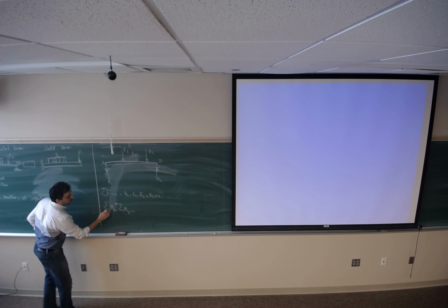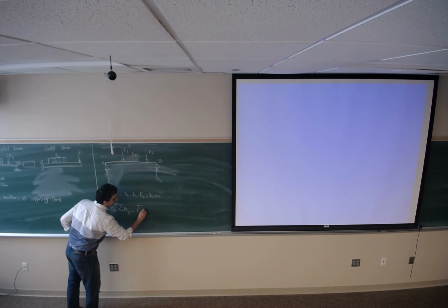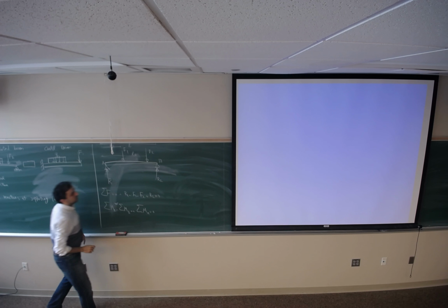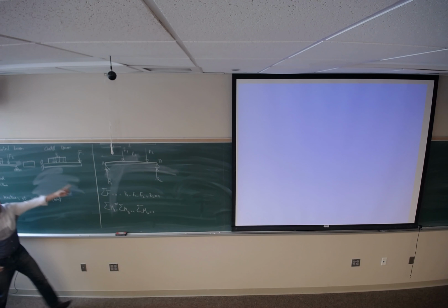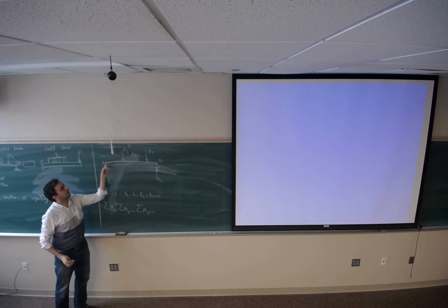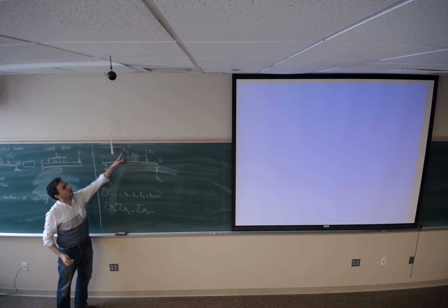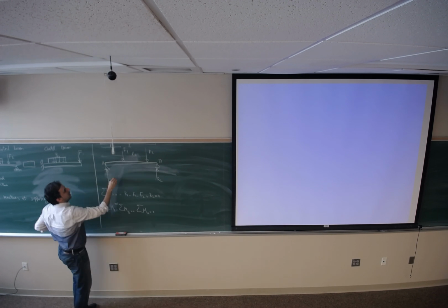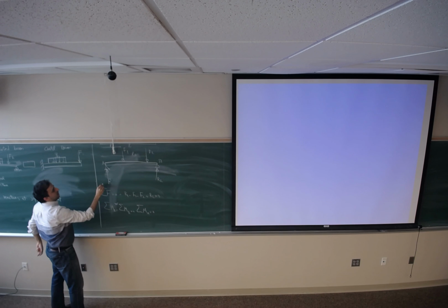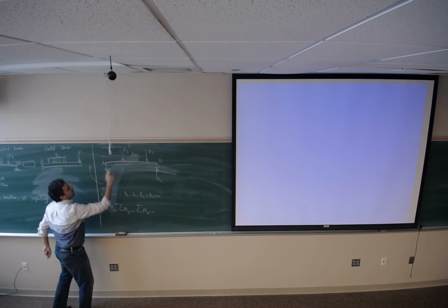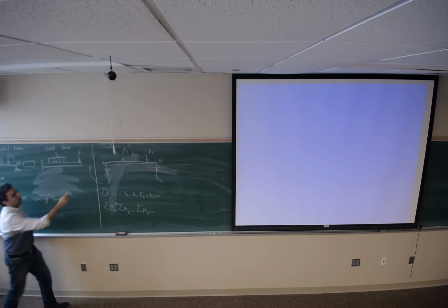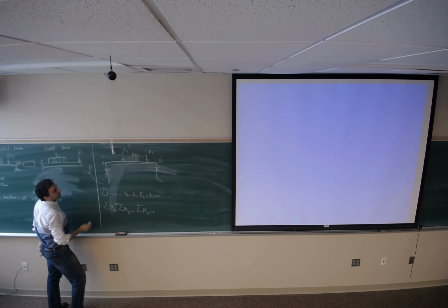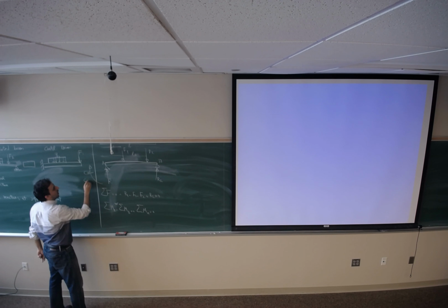I'm using sigma M with respect to point A equals to 0. So what would be the external moment about point A? I apply force F1 at the distance of L1. Force times distance is making bending moment, making the beam rotate clockwise. Clockwise is negative, counterclockwise is positive.